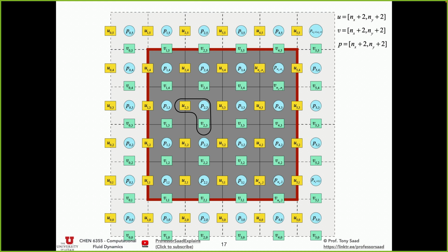They're ghost cells. They're placed there for convenience. In fact, for the most part, we're going to just set them to 0 and never use them. But occasionally, for a certain boundary condition, we might need to put a value in the ghost cell just to make post-processing easy or some calculation easy. We'll leave it there for memory. And it will make all of our array analysis consistent.